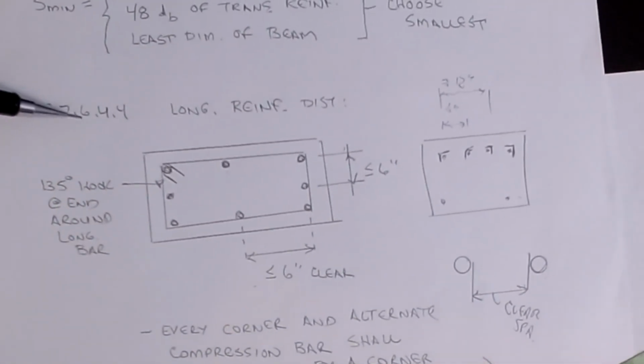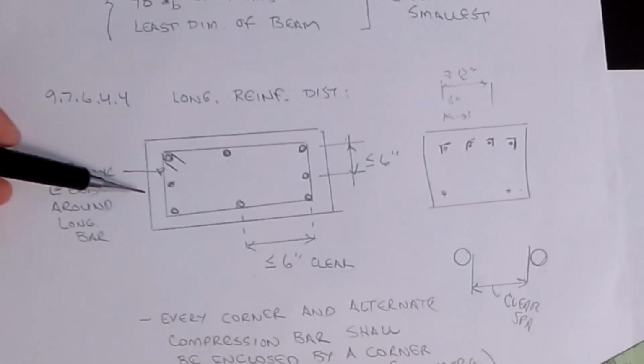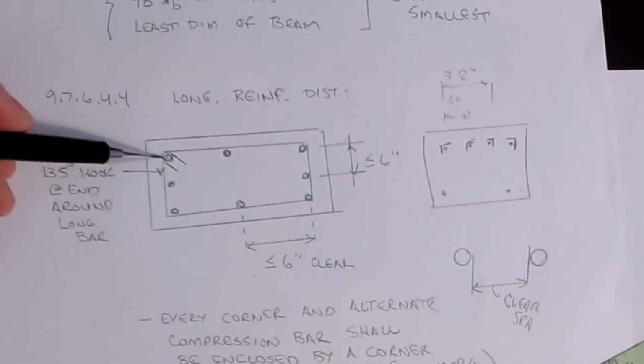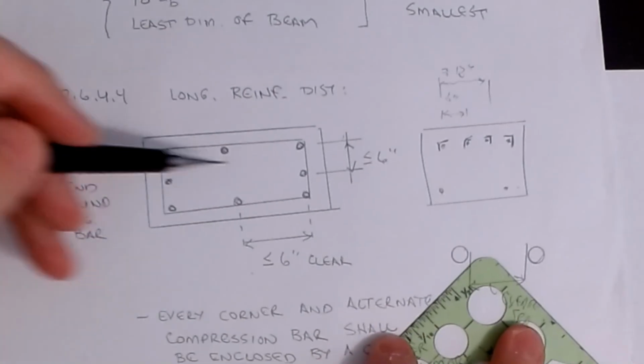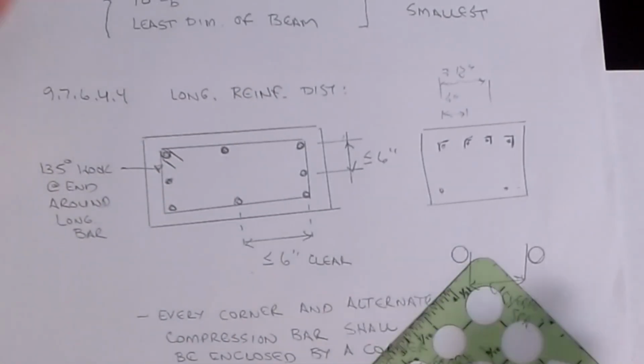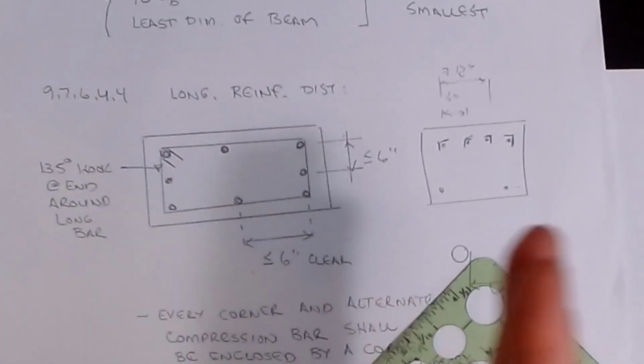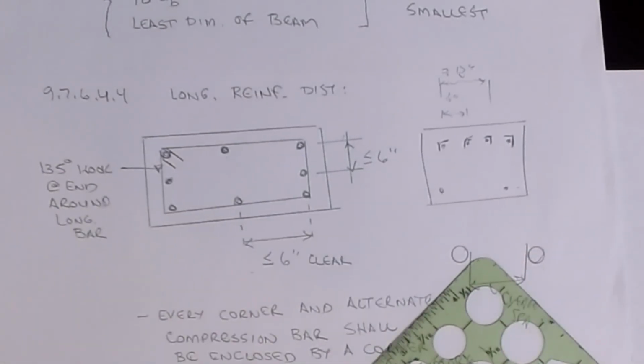And so this one produces some challenges because, for torsion, instead of using two number 10s around the cross section of a beam that's fairly big, it's going to make you spread that steel out so that I'm instead using 5 number 6s.